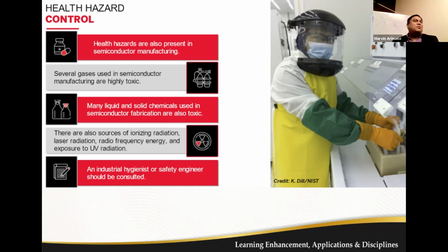And we are using a special type of tube, coming from the US, without joint. Normally in a piping system, we will introduce a joint, right? But for the chemical piping system, we use a pipe without any joint at all. If it needs 100 meters, no joint. The double containment, of course, is properly sealed. Not only that, for some gases, I think hydrogen gas, we use stainless steel pipe, and we are using a special type of welding, TIG weld.